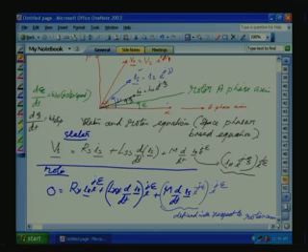So here if you see, the voltages of the stator and rotor we defined with respect to the alpha beta axis, where the alpha is placed along the A phase axis. This is called the stationary reference frame axis. Because alpha is placed along the stator A phase axis, that is stationary. So it is called the stationary reference axis, that is the alpha beta.